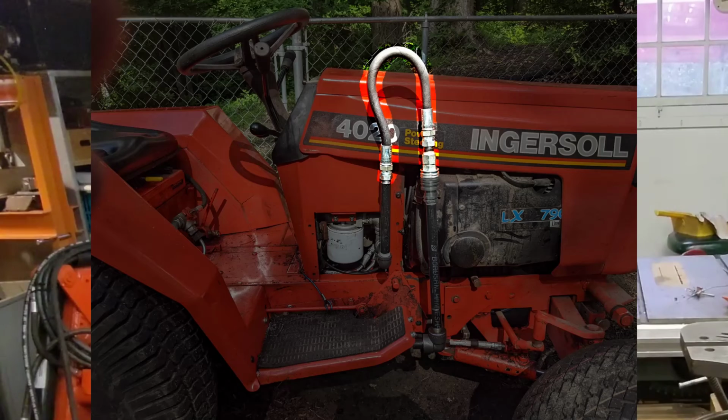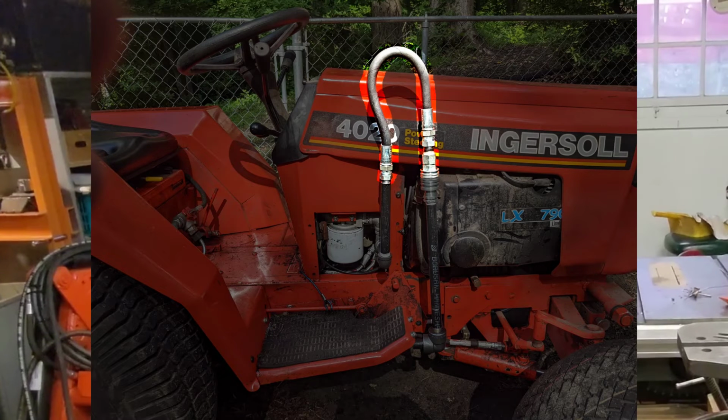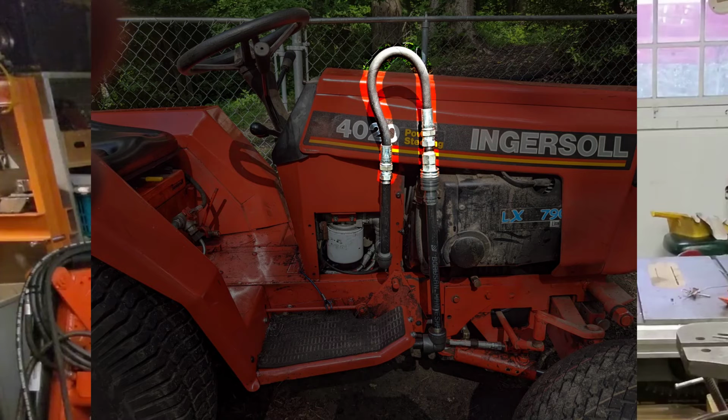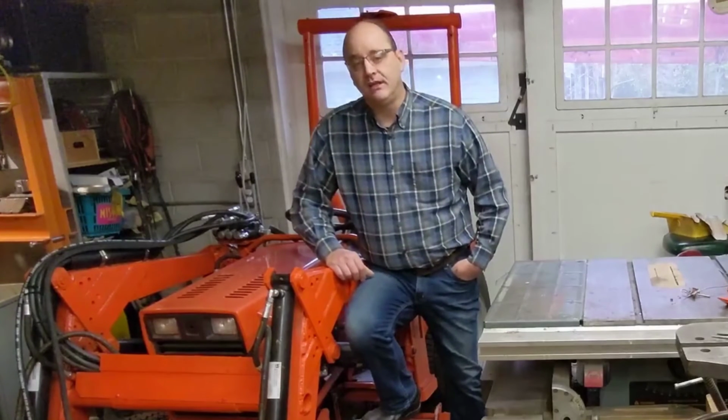With the loader detached, one of those hoses will hook directly from the pressure supply into the return to tank fitting. The high pressure flow has to always have a path to make its way back to the tank. So there must always be a connection from the pressure fitting to the return fitting. The flow can either route into and through the new loader valve, or the flow can be directly connected by a single hose.